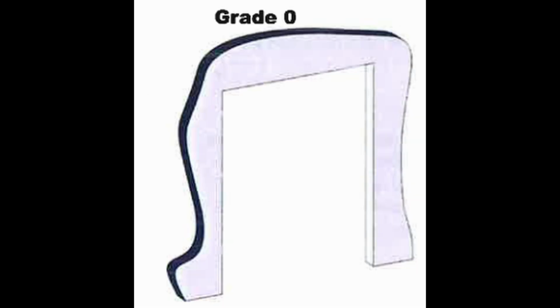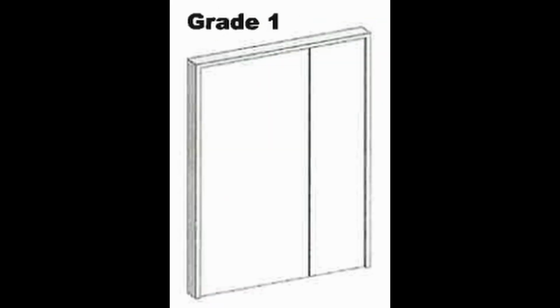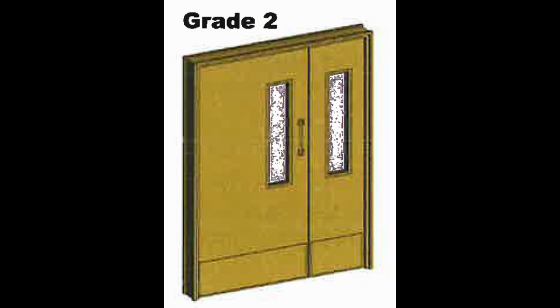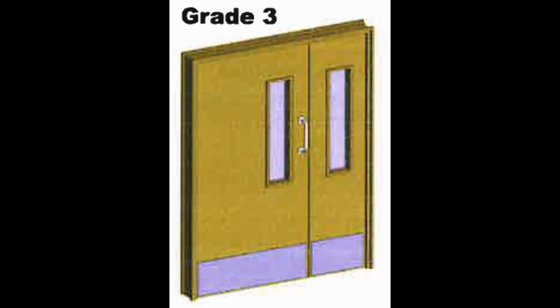Component grading. The complexity of components. All components should be quality checked, graded, and named before being used in a project. A well-designed family should be flexible within a defined scope, but should never attempt to cover all possible scenarios. A door family with dozens of parametric permutations may seem powerful, but on large projects it becomes unmanageable. Often, supplementing simple geometry with high-quality 2D detail delivers far better results.